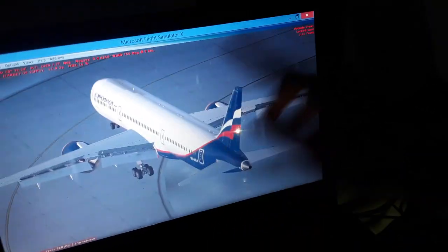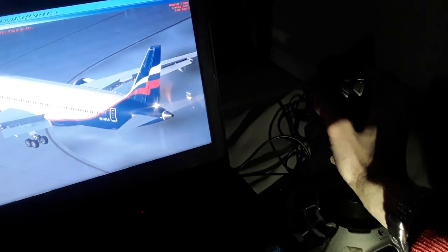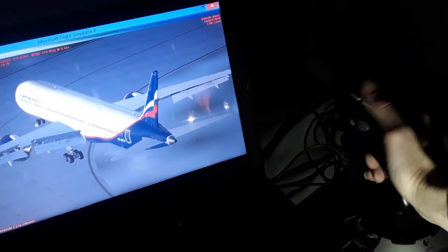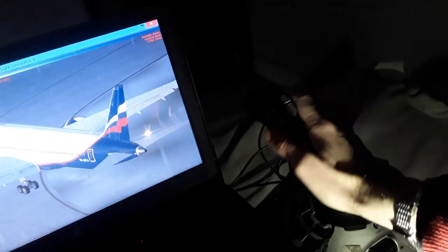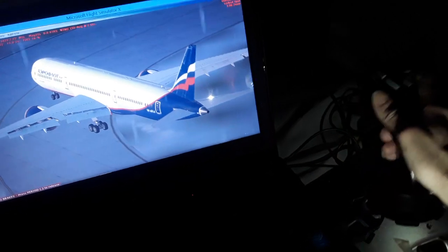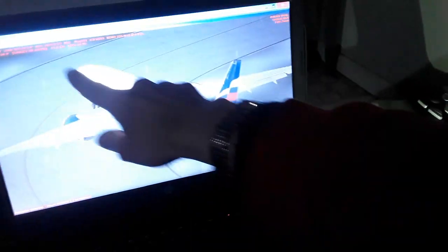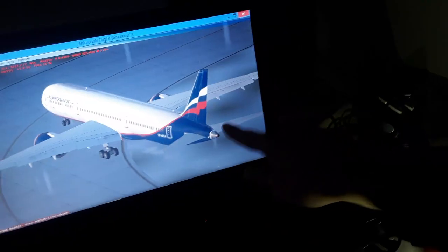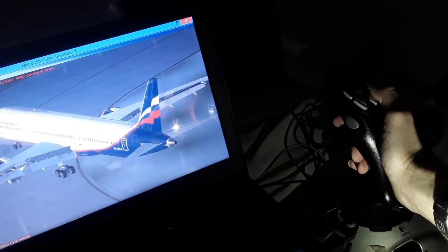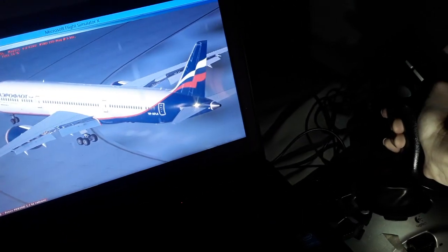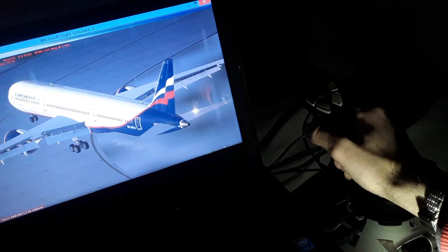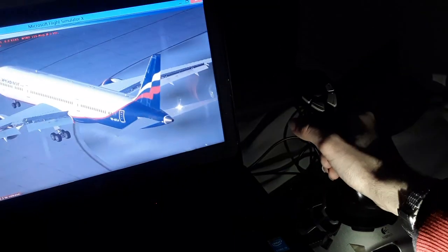Also the rudder. So the rudder is on the vertical axis through the center of gravity. It is also the yawing axis, to make left and right yaw turns. We have also the longitudinal axis. That's the rolling axis. You make turns to the left and to the right through the longitudinal axis. That transverses also the elevator and the vertical stabilizer. So you make turns left and right like this using the longitudinal axis of the aircraft.